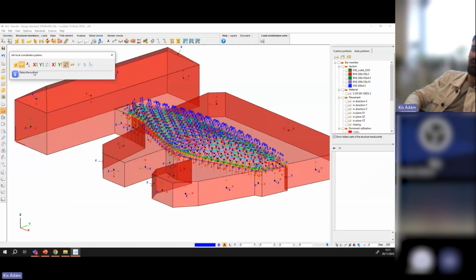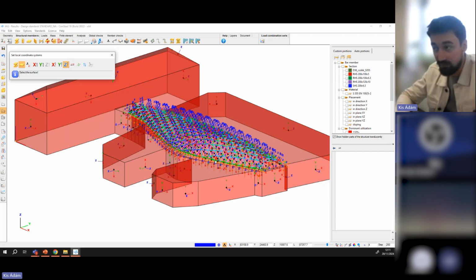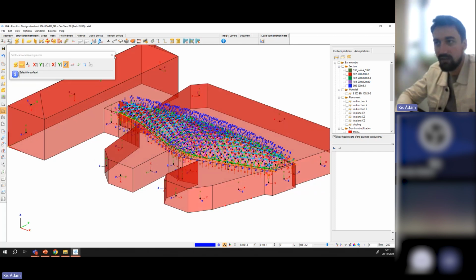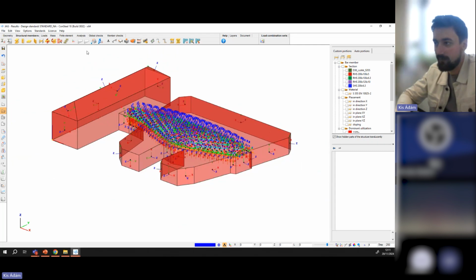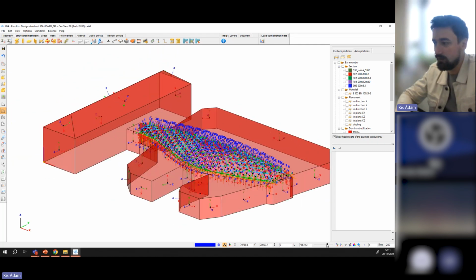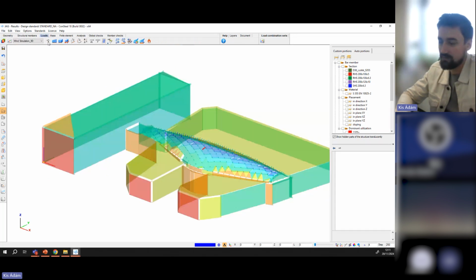Obviously we are working with surfaces, so you select the surfaces and you just have to point an inner point in the building, and all the surfaces will be pointing outwards. So it is really convenient, but you have to make sure that your building is modeled adequately. So this was actually the second example I showed you in the presentation.